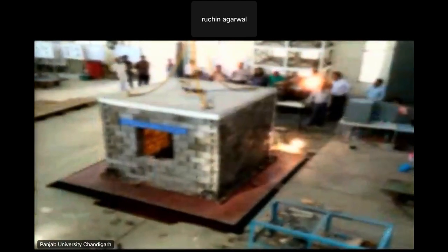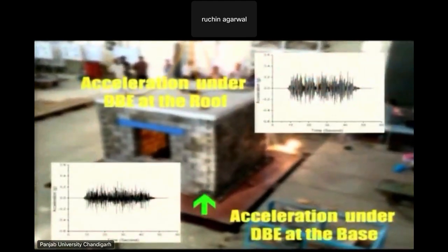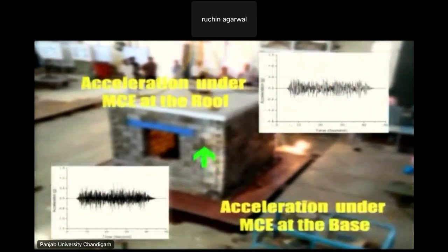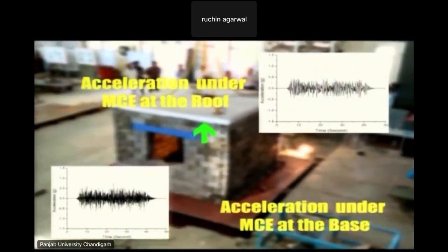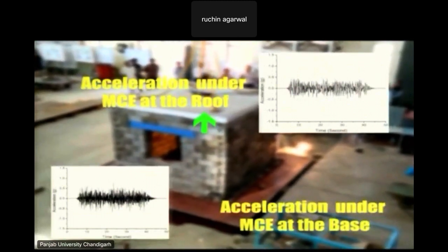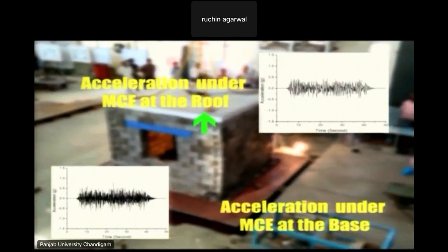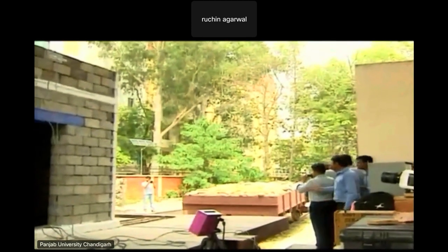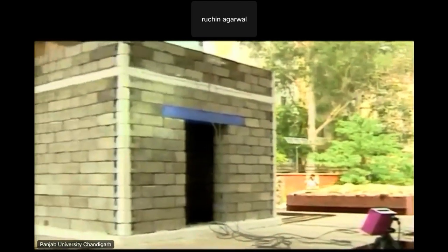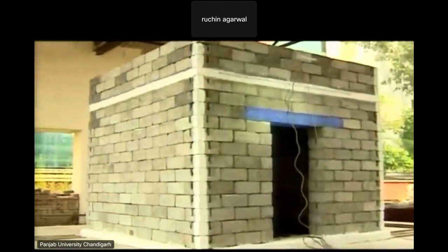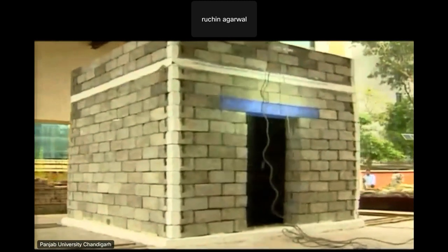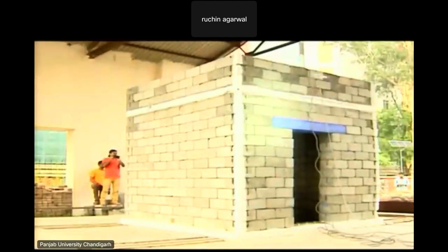Along the height of the model, there is a reduction in maximum roof acceleration as compared to base motion, without any damage in the model. The energy imparted is completely dissipated through friction and viscous damping of the viscoelastic links. The model retains its original shape and position after the tests. Further, increasing the severity of the test, single-storied and two-storied models are also tested on the shock table by giving impact type of loading. Three consecutive shocks of increasing intensity are applied.